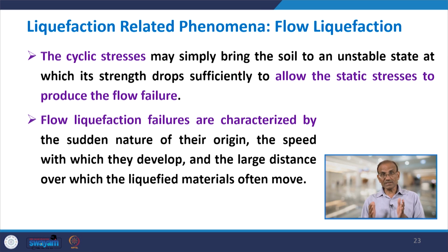Once flow liquefaction occurs, it is going to be highly damaging. Its damage is not going to be insignificant. On the other hand, the damage caused by cyclic mobility may be insignificant or may be highly damaging. So, the range is wide, but for flow liquefaction, if it occurs, it is sure the damage is going to be huge.